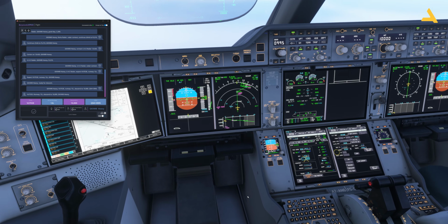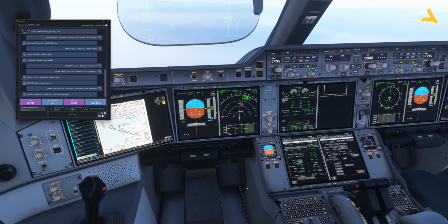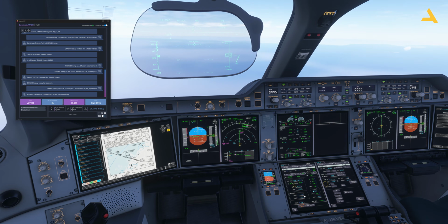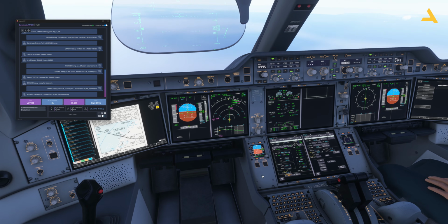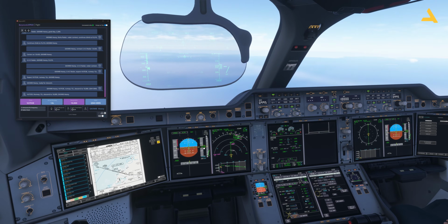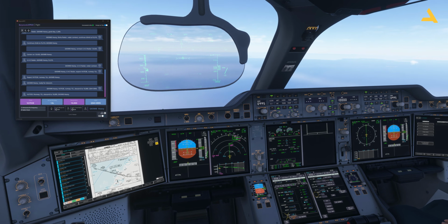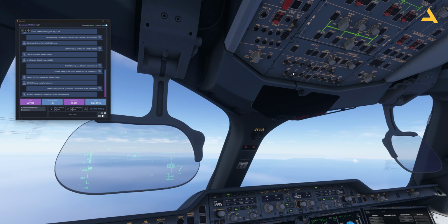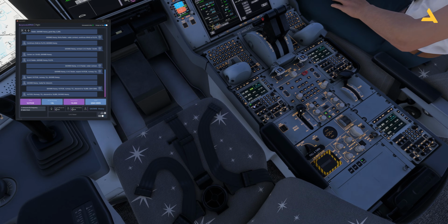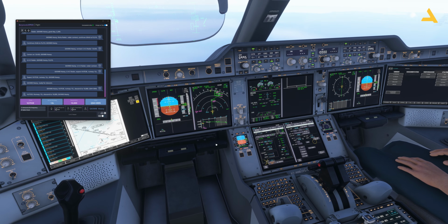Dubai. Now I've changed the frequency. Now you can see that I've got the wind information, the QNH, and plus the transition level was 150. Now the plane is going to cross 10,000 feet, so I can turn on the seatbelt signs as well. Set to auto. I can turn on the lights for the landing. That's it. And arm the ground spoilers. So I just reverted back to the frequency to which I was actually tuned in.